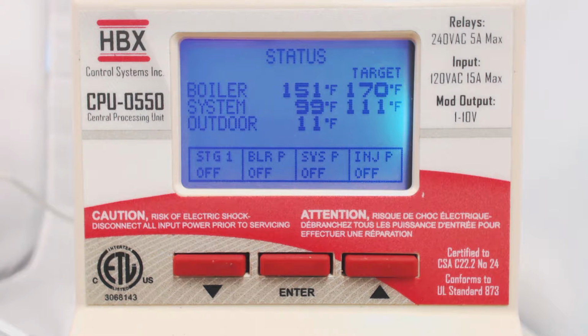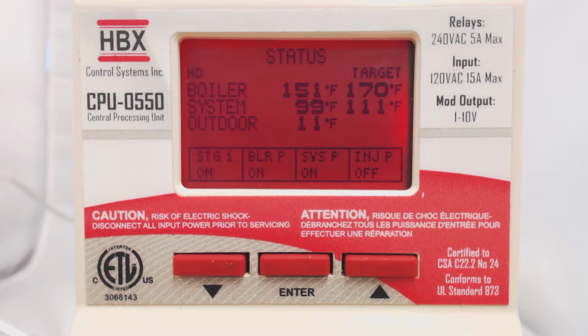The screen will change color to let you know what the control is doing. White or light blue means there is no demand. Dark blue means there is a demand present but the boiler is satisfied. Red indicates there is a demand and the boiler is running. And yellow means a heat demand is present and the boiler is running but in boiler protection mode, which indicates the boiler is below the minimum boiler temperature set by the user, and will disable any mixing devices until the boiler rises above the minimum boiler temperature.